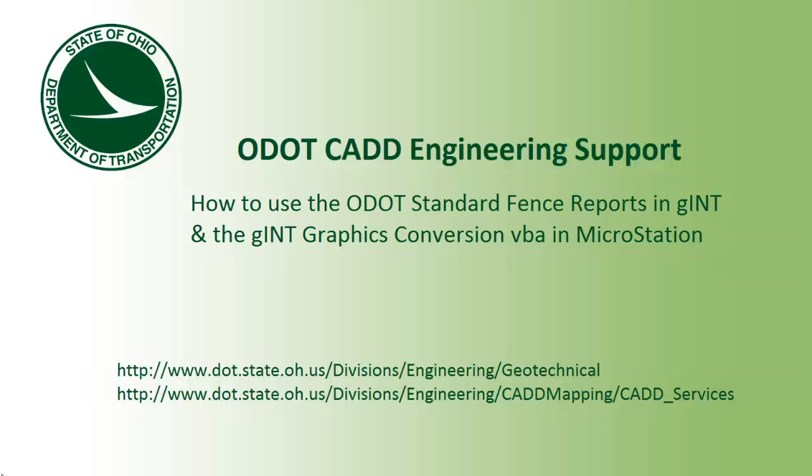Today I want to show you how to use the ODOT Standard Fence Reports in gINT to export boring graphics out of gINT, how to use the gINT conversion VBA in MicroStation to convert those graphics to meet the ODOT CADD standards, and how to use the Move to Models tool to set those graphics up to be used with the Place Boring Graphics VBA to place the boring graphics on your geotechnical exploration sheets. So let's get started.